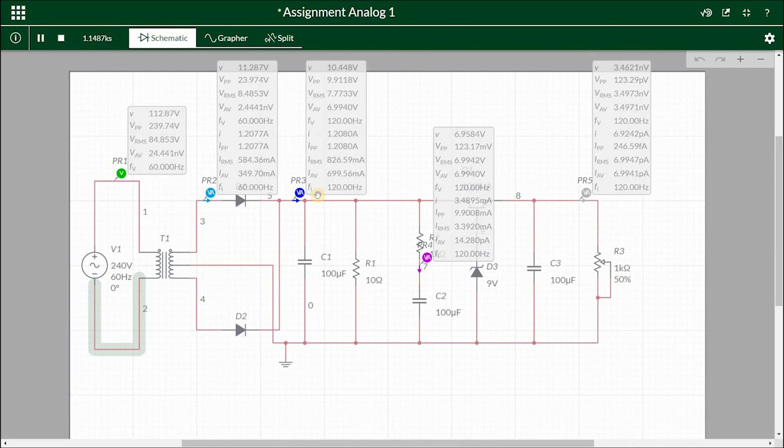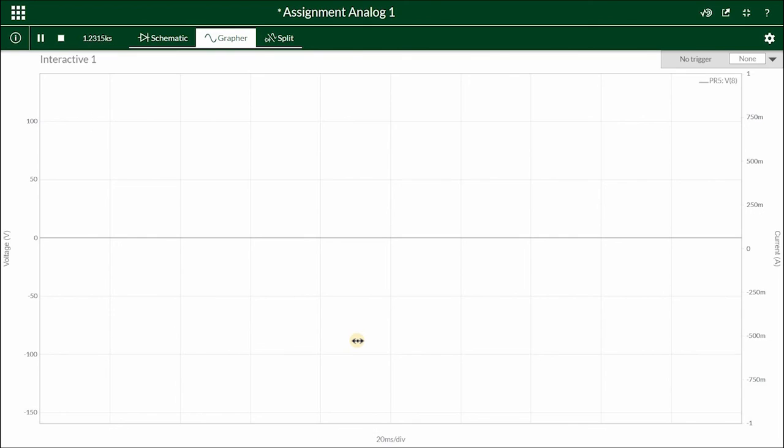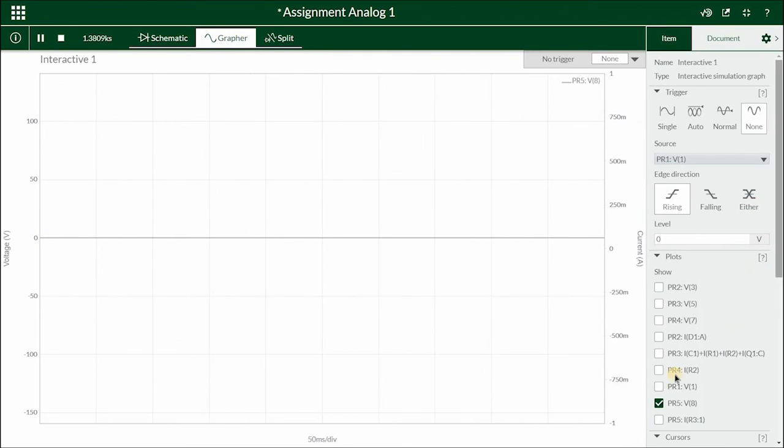As we go to waveform 5, it is the part of the circuit to which the DC power is delivered to perform useful operation. Looking at the graph, it might not be so clear to see, but if you look in the center here, where the cursor is, this gray straight line is the final waveform of the DC output. And as you can see here, it is much smoother compared to the previous waveform 4. It was pink and there was a minor ripple which was slightly above the x-axis, which you can do a comparison here.